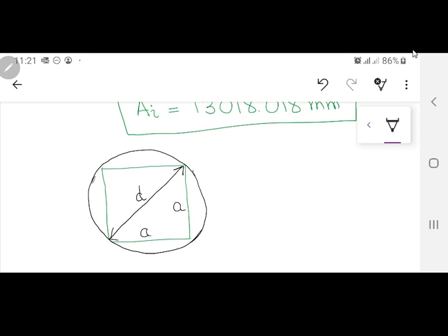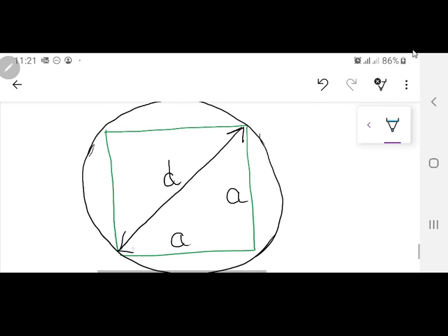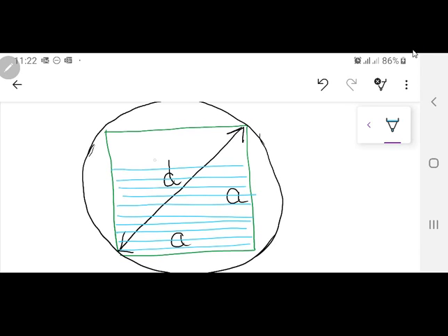Now before I proceed on forward, there is one problem over here. Since you are going to stack laminations, you are going to have laminations over here, and those laminations are going to be in this way. Now these laminations can have a thickness from 0.8 to 0.9 or 0.95 millimeter or even 1 millimeter, or maybe if you are a bad manufacturer, then you have a little bit more thickness. Smaller the thickness, better the manufacturer or better core losses you have.